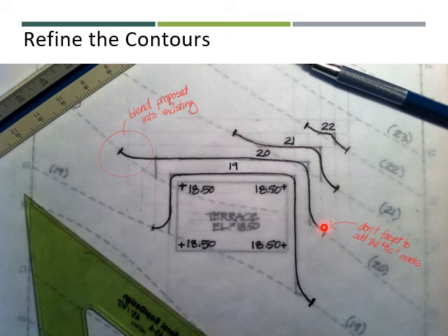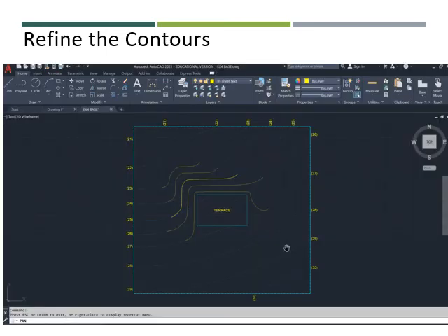Likewise, students try to get an official answer on what size this radius needs to be. And again, that's an artistic thing and part of the design process. You will get to choose that as you're doing the design. However, you do have to blend it back in to the existing contour, and you do have to add the tick marks in. The process in AutoCAD is really pretty much the same. So in AutoCAD, you can see that the same technique is used.